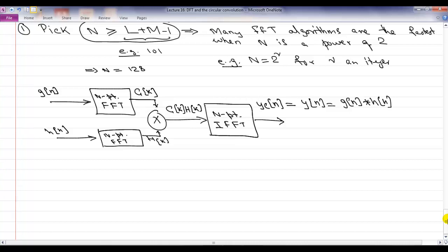Now, when we do this chopping up of the signal, we have to be careful how we align back the outputs of these chopped up pieces. That is a really involved topic that we are not going to discuss in this class, but it is important for you to keep in mind this aspect: for signals that are either too long or for signals that you need to process in real time, you do not apply this procedure as it is, but rather you go through the process of chopping up the signal.